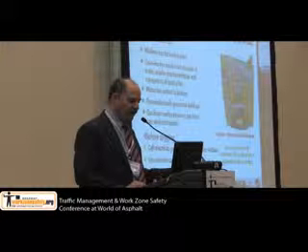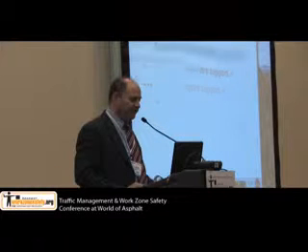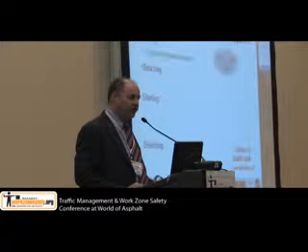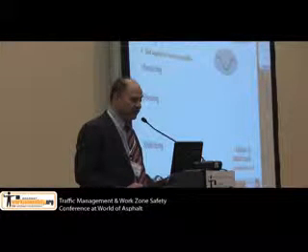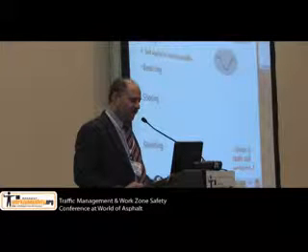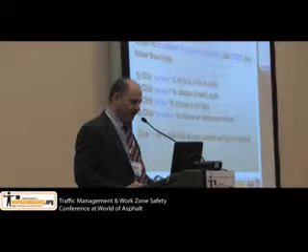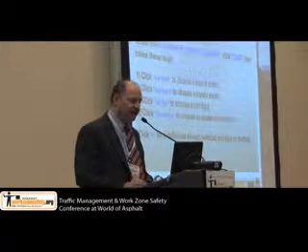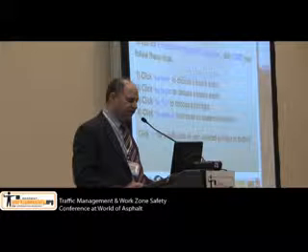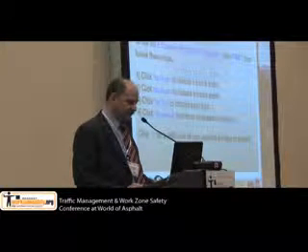So first we define what the hazard is, and then we have 2 slides talking about how you prevent cave-ins, because most of the trench fatalities come from cave-ins. You can slope the soil, and we have a demo here. This is an excavation calculator to show people the difficulties, or what it takes to slope appropriately.